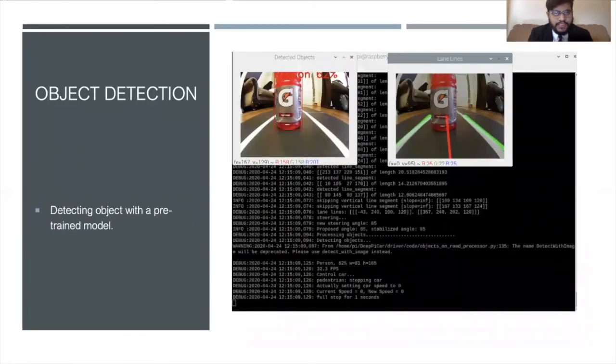With object detection on the edge, at the moment, Edge TPU can only support the TFLite format of the model. So if we have a model in any other format like .pickle, .pb, .onnx, or any other format, these models have to be converted into a quantized format.